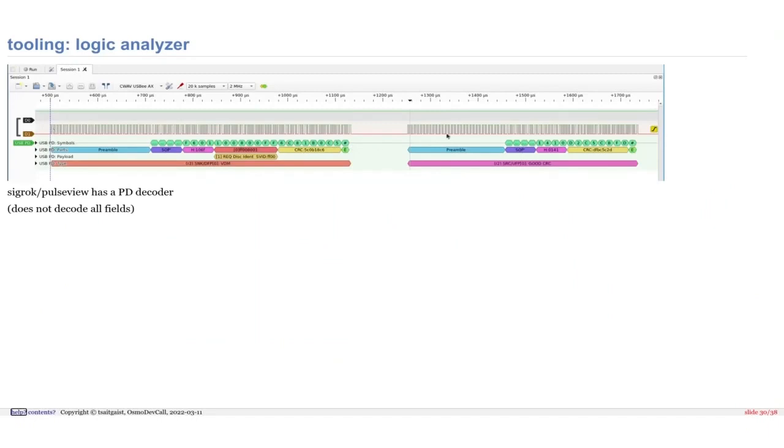After every packet, the other side has to ACK any packet with a good CRC. This is just taking the sequence number from the previous packet and saying, okay, I got your message. This is just an ACK. This is not the reply yet. We'll have a look at the reply afterwards. And this whole message, because they probably wanted to keep the same format, also has a CRC.